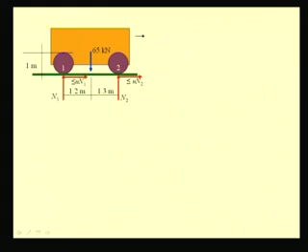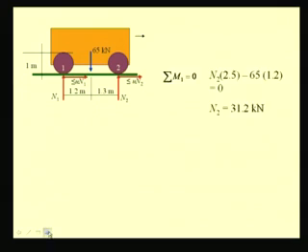We know this geometry, that is, the location of the CG of this vehicle: it is located at 1.2 meters from the rear axle, 1.3 meters from the front axle, and 1 meter from the ground. So, we write the equilibrium equation. Let us take the moment summation about this point 1.